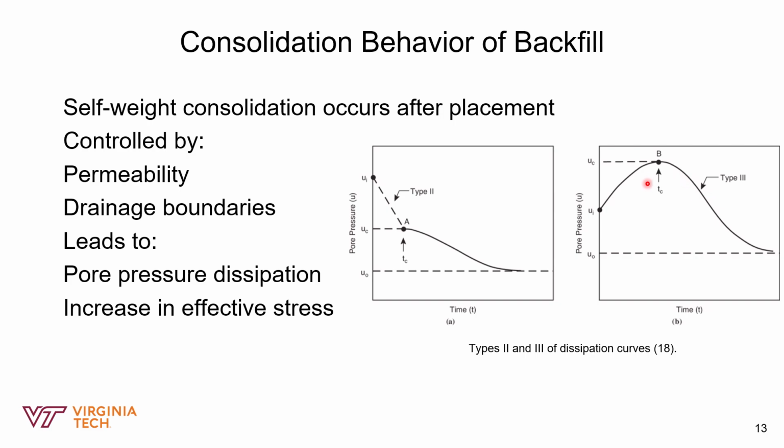If the pressure stays high, then liquefaction can happen, which we will talk about in the next few slides. So this is the ideal reality, I mean. When we pour the paste, the pore pressure is initially high, and as time goes on, the pore pressure drops because the cement is reacting with the water. The paste is losing water, and so pore pressure keeps decreasing.